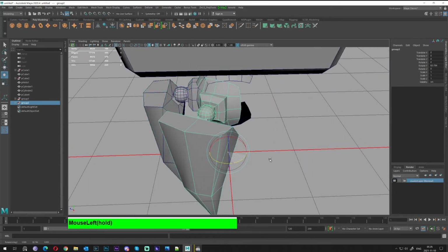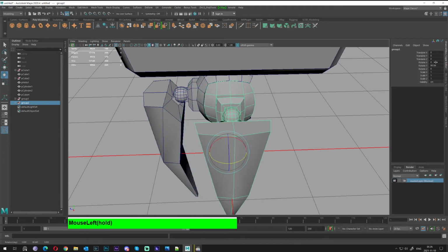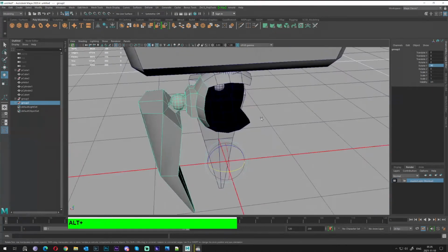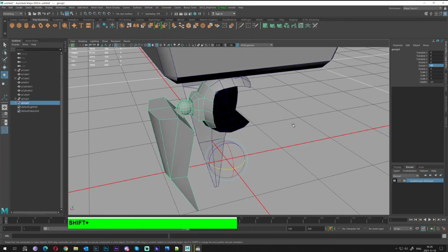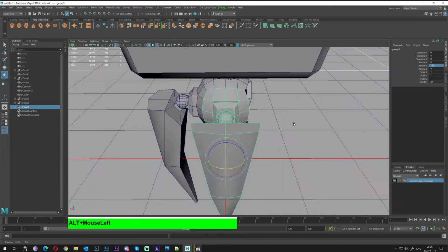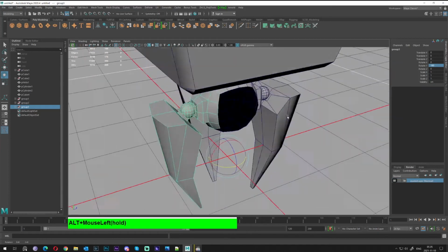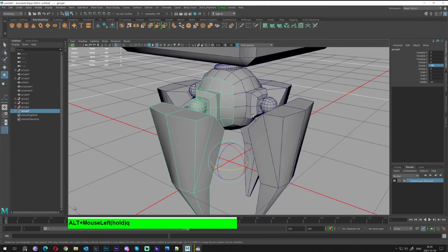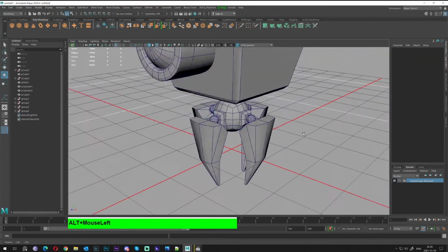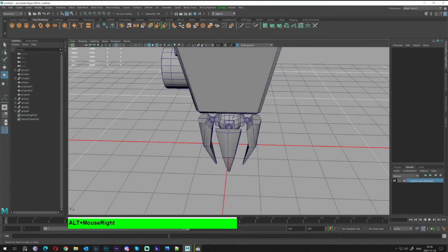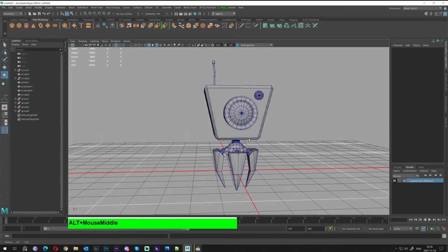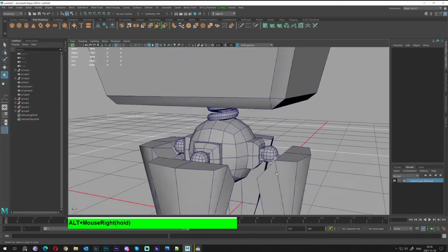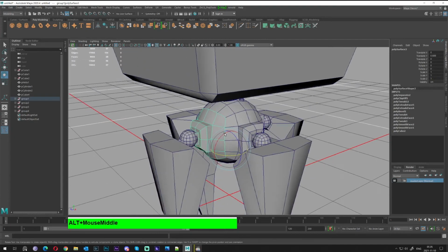Now we press E in order to go to the rotation key, and we can move everything by 90 degrees on the y-axis. What we can do next, just press Shift and D. As you can see, it will place in the same increment, and Shift and D again. Awesome. As you can see, we have our small robot.